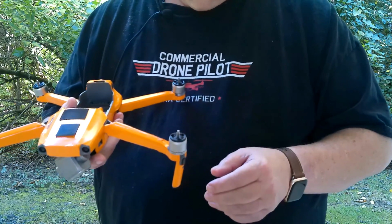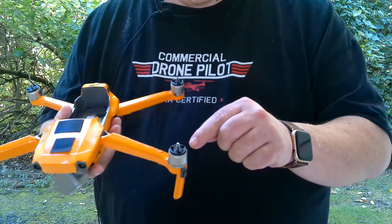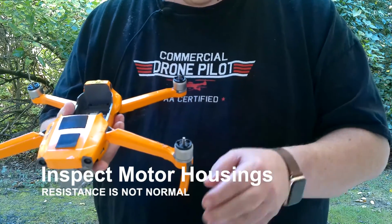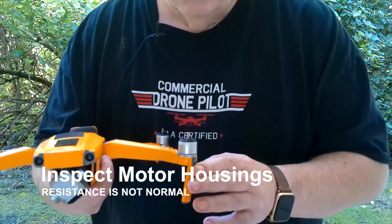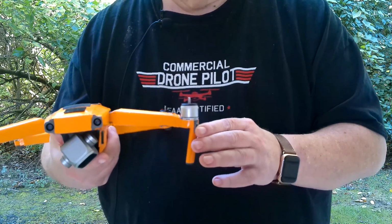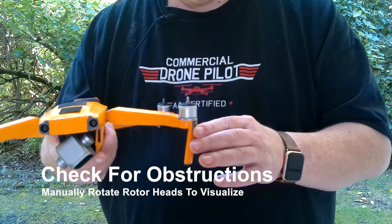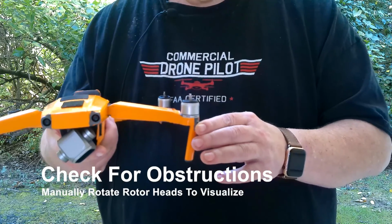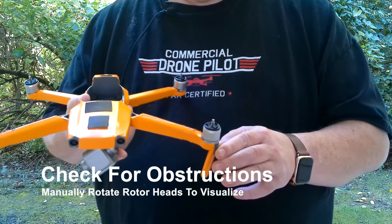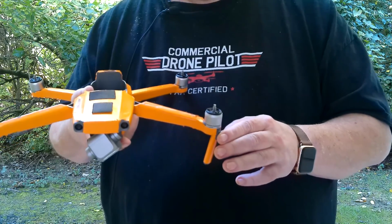We need to look at the rotor motor housings. If you'll look inside one, you'll see that there's space below the upper portion of the housing where debris and dirt can become lodged and prevent your rotor from turning.